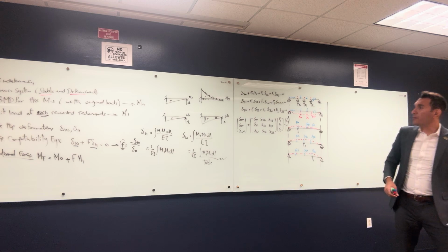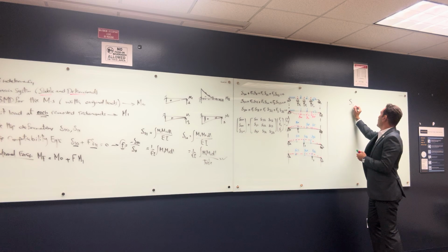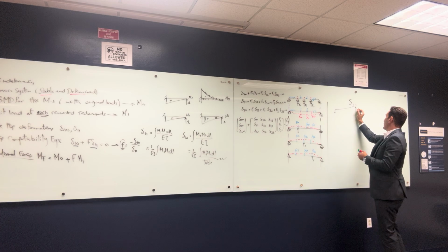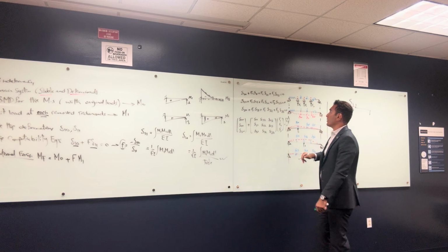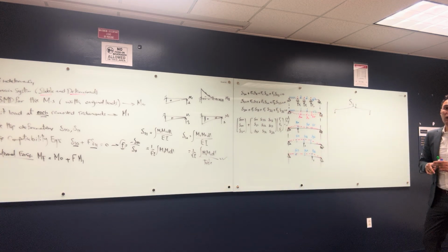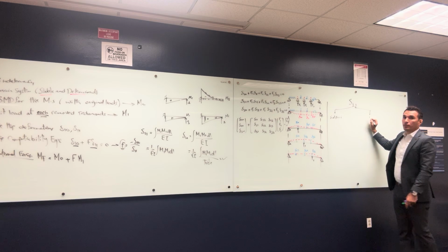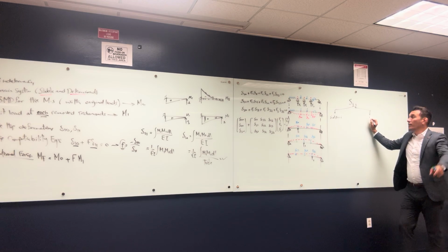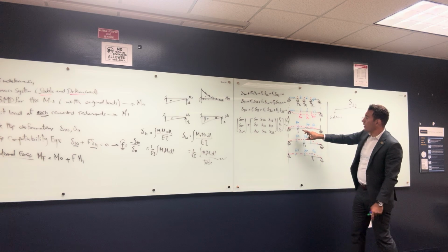All right, I put something here to generalize the approach. Delta IJ. Do you guys understand what is I now and what is J? Like here we put a number and here we put a number. Based on your understanding, what is this number? The point. The point that we are dealing with. So that means delta at point I. How about the other number? This is where the unit load is at J. Okay? So this is the point that we are measuring the deformation at.